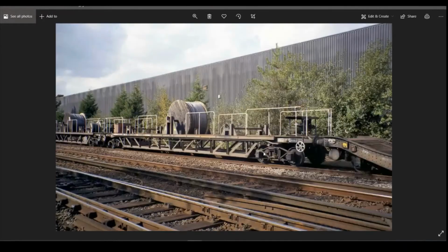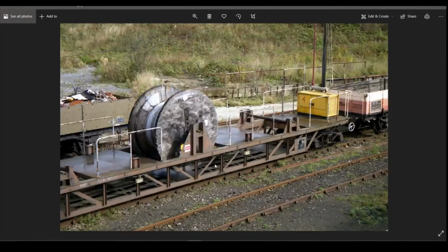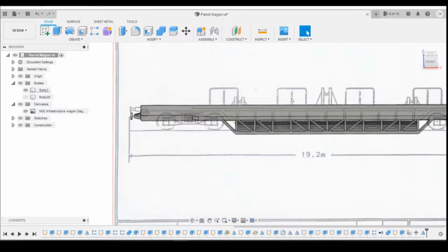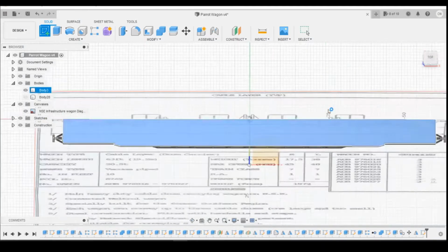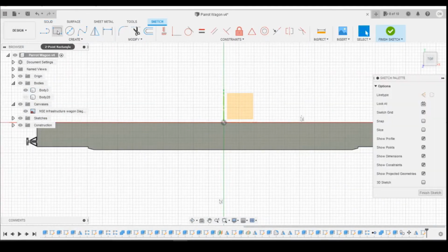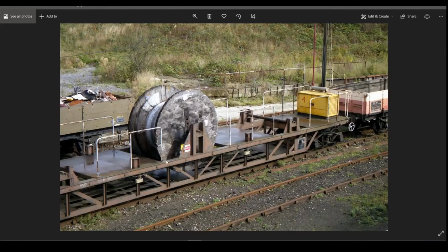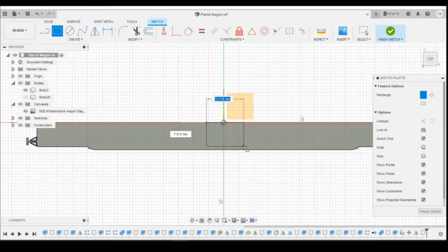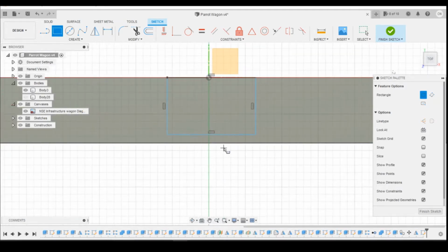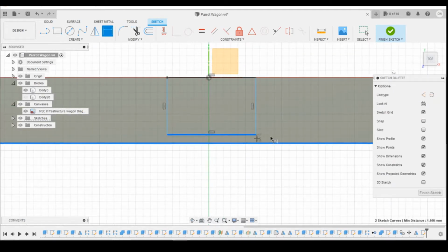If we look at it, the middle one, and then the ones either side of those. So there's the midpoint, obviously. Create a sketch on the top surface, and I'm just going to use a rectangle to draw across like this. Now, obviously we don't want to come all the way to the edge, we need a bit of a gap on the outside. So we'll create that gap there like that. I'm going to find the distance there. I'm just going to give it a 1 millimeter thickness.